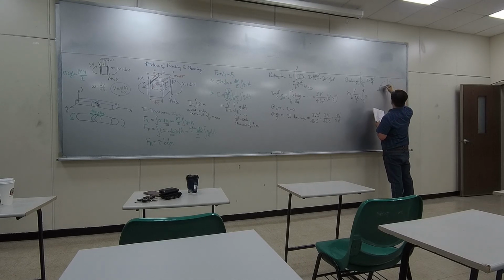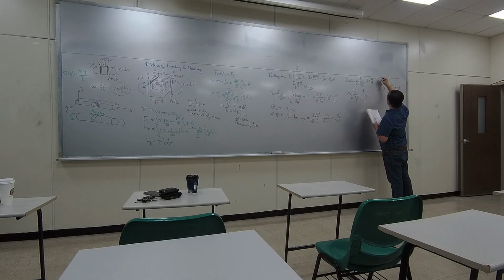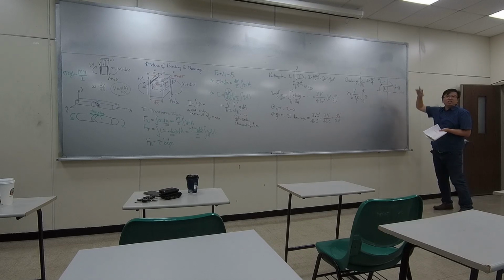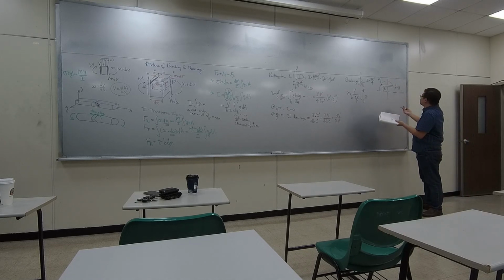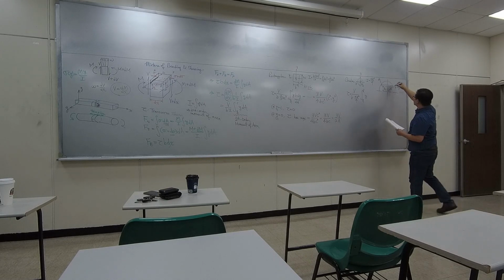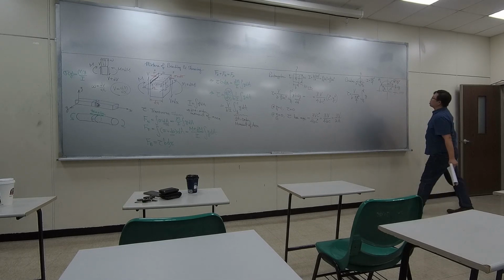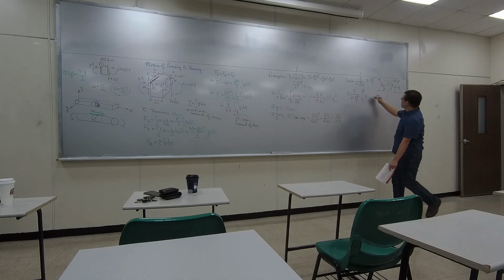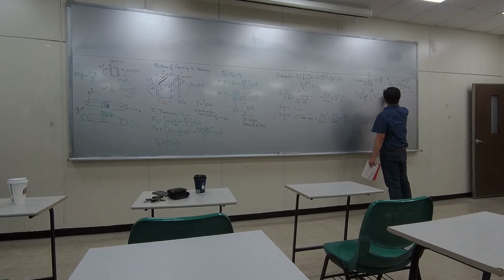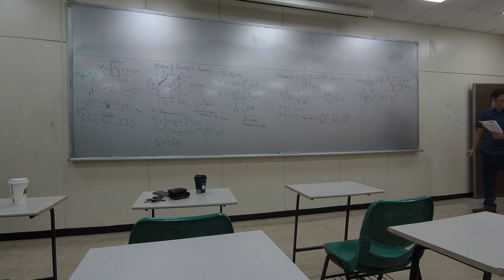Over here, this is your y1, here's your dy, and the area right here is dA. It's changing at different positions. One way to get it is to use r right here, and the distance right here is the square root of r squared minus y1 squared. So the width is going to be 2 times the square root of r squared minus y1 squared, times the height dy.